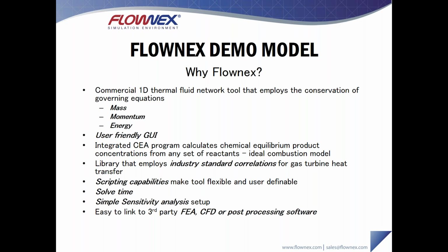If we look at some of the other reasons why we use Flownex, the fact that we have that integrated CEA calculation or chemical equilibrium calculation is super helpful. There is a large library of industry standard correlations for gas turbine heat transfer already within the tool. That being said, we recognize that many companies have been developing their own correlations for many years, and for that reason, we make it flexible and possible for people to script in their own correlations or user-defined functions.